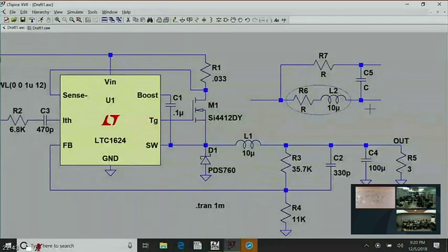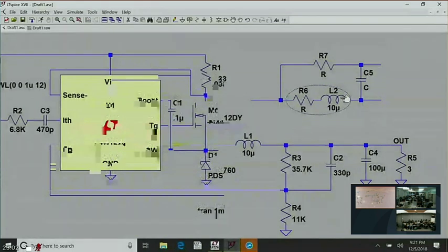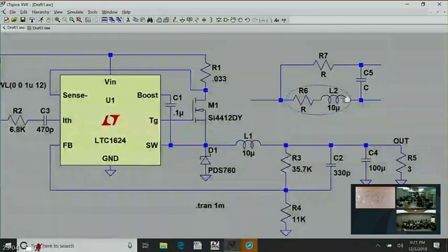And the waveform you get across the capacitor is the waveform that you would have had across the ESR had that ESR been a discrete lumped constant. Okay, it's an important technique because you're taking a great big huge square wave and integrating it down to exactly the waveform you want. It's a great technique. I won't use it today, but if you ever actually do design switching power supplies for a living, it's one you'd want to know. That's current inductor sensing.